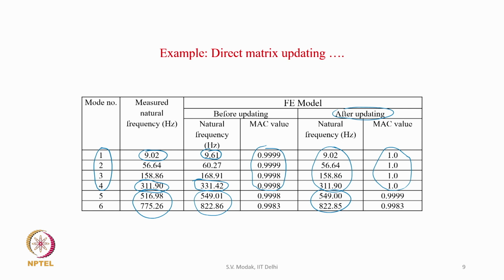A direct matrix updating method reproduces the data which was used in updating. However, for the data which was not used in updating, the natural frequencies and mode shapes of the modes beyond the updating frequency range, not much improvement in their correlation is seen. So, this is not a desirable characteristic of a model updating method. Ideally, we would like some improvement in the correlation of modes which were not used in updating.